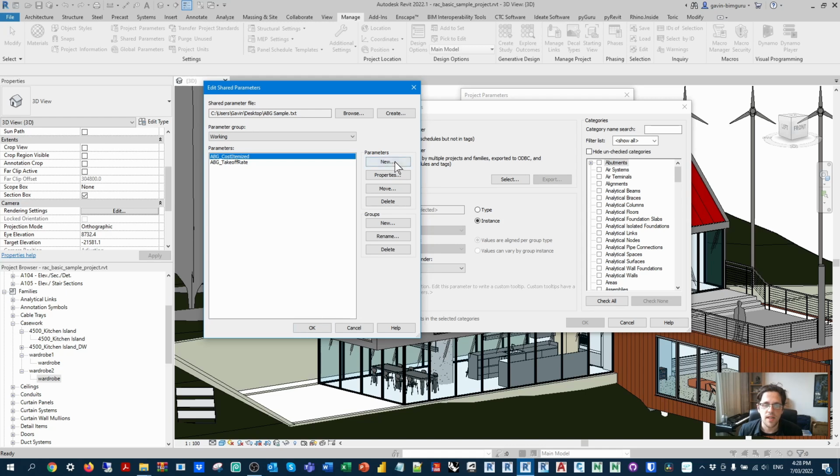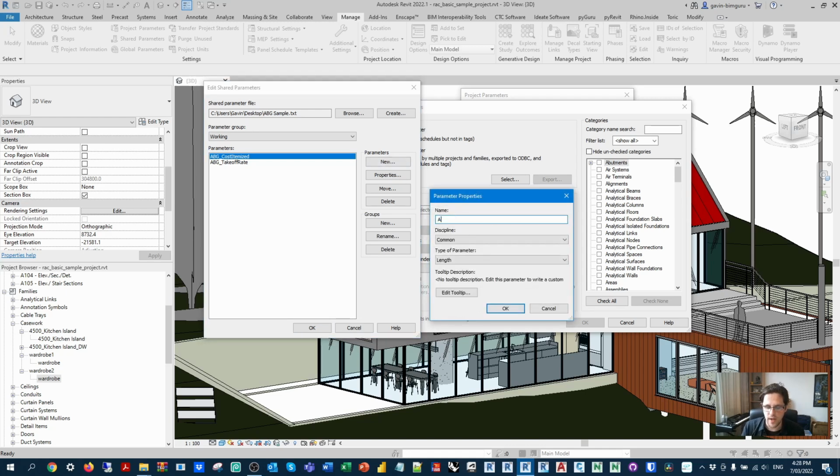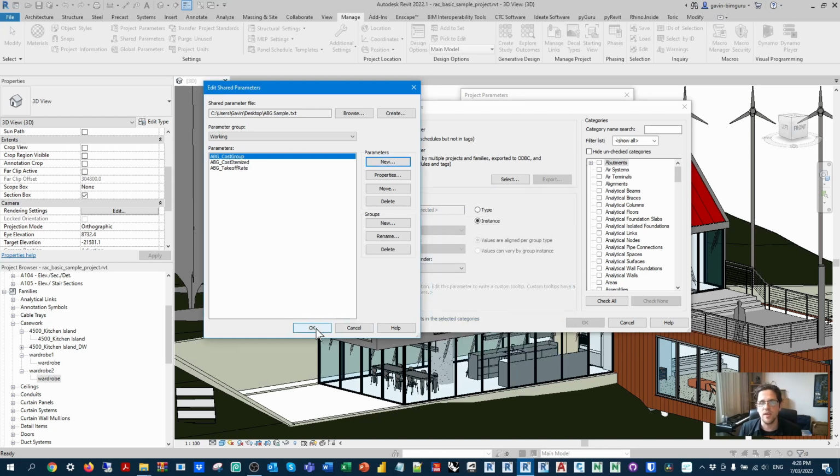The last thing we'll do is we'll add a cost group, because we want to break down these objects into logical sets of objects that we can then compare on a group basis. So for example, if I just want to look at the planting or the landscaping, or I just want to look at the facade, I can isolate them using cost groups. Now you could use a classification system and assembly codes. That's another way that larger projects usually manage this. I just want to keep things simple for this demonstration.